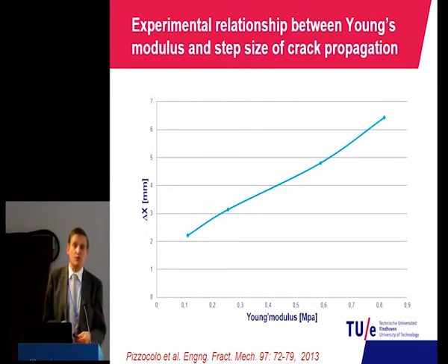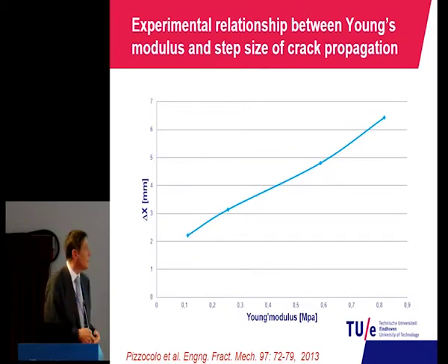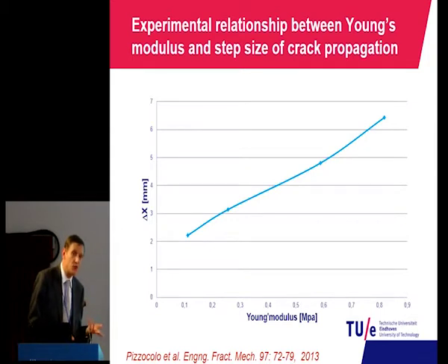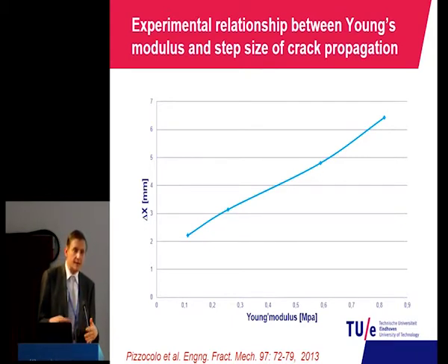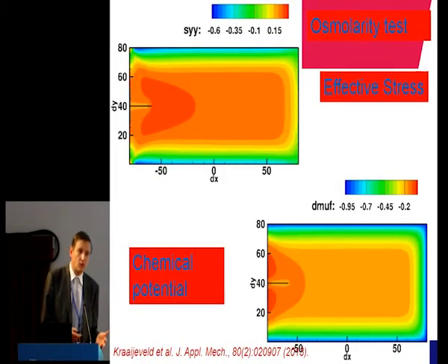And as the fluid never cracks, only the solid can crack, you get a protective effect of this fluid against cracking. Now this protection comes in, but only temporarily, because this tensile traction within the fluid causes fluid flow. And as the fluid flow takes place, you get propagation.